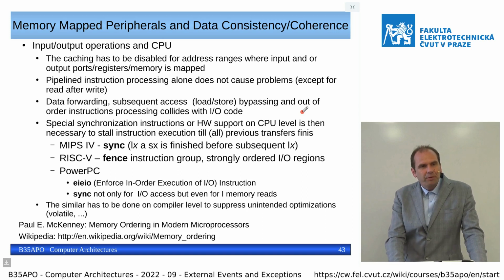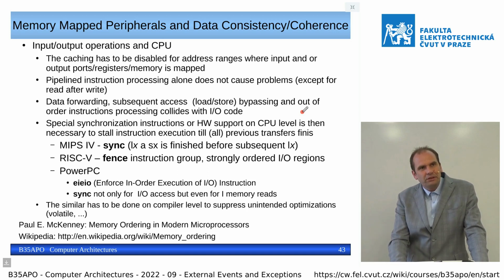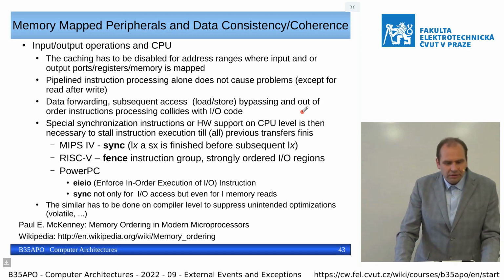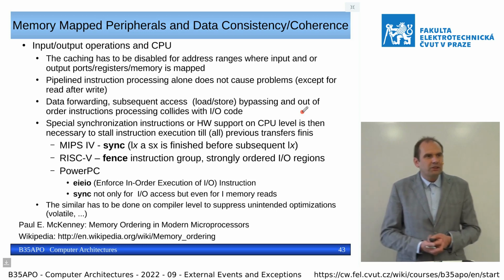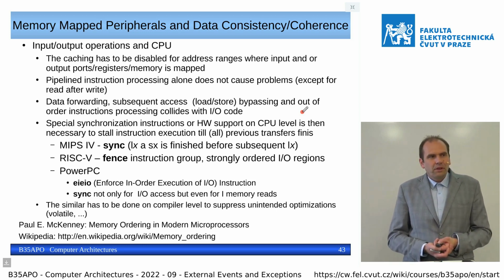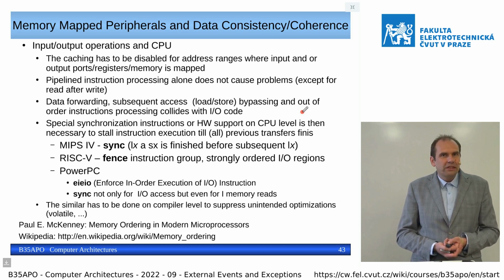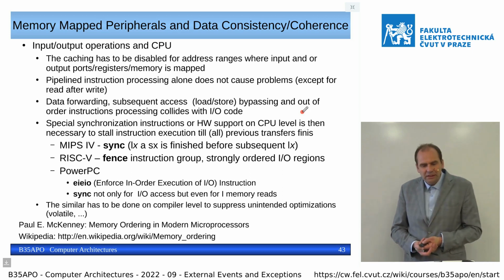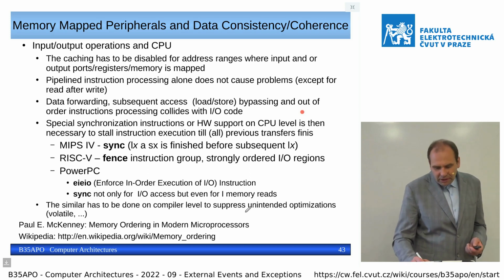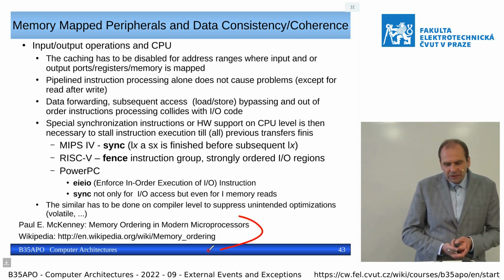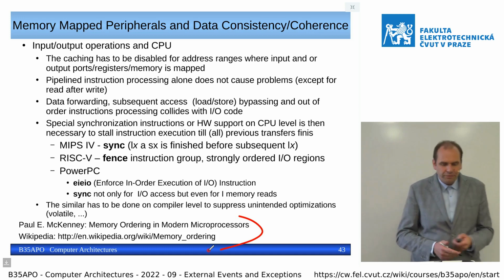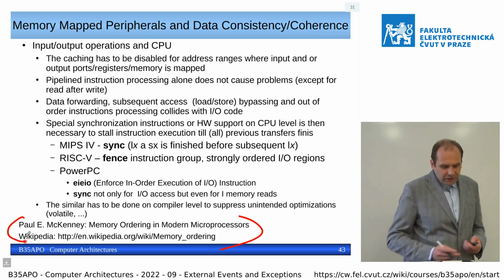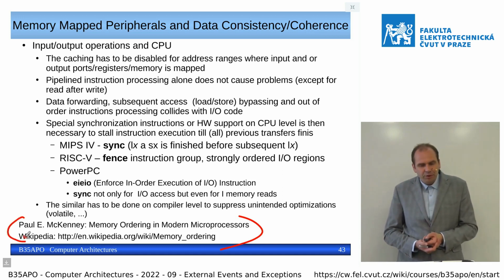The second problem is that today the processor executes instructions out of order, and it is possible that they reorder the actual read and write operations to the memory, because for the speedup, it ought to be done this way. Each architecture has different rules. It is really, really complex stuff. It is probably the most complex. The memory models are probably the most complex part of processor system design and then programming.